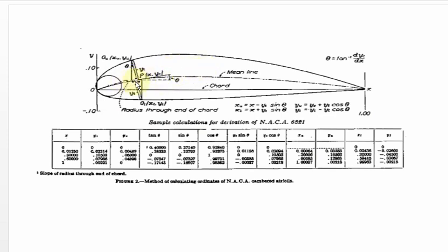So you have to draw the tangent to the mean camber line from the leading edge, and similarly from the trailing edge. Then we use the Pythagoras principle to find sin theta and cos theta, because from this only we manually identify the coordinate values. For that purpose, we have to know these theta values.